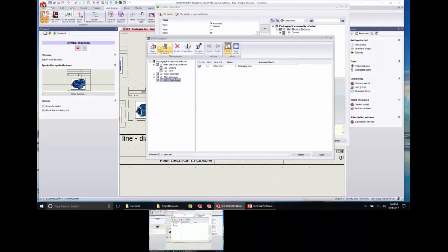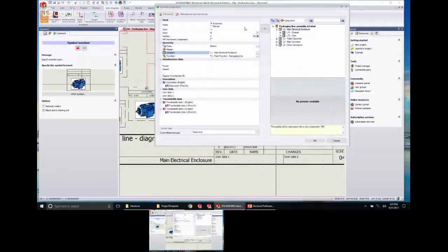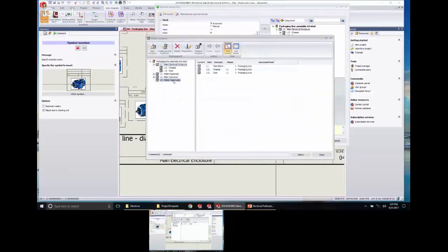You can go to this location dialog, and here's where you would add new locations or create several. And then after you do that, I'll show you. Well, you can go in just like I'm doing right now. So the motor by default was in that main electrical closet, but now I'm just going to go to the ellipses again. So main electrical enclosure here. Just went to the ellipses, and now I'm going to pick and choose which location I want.